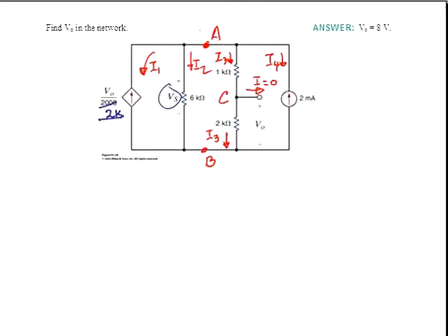We see in the circuit that VO by a voltage divider relationship will be 2K times V sub S, the total voltage between nodes A and B, divided by 1K plus 2K, the series combination of resistors, or VO is equal to 2/3 Vs.